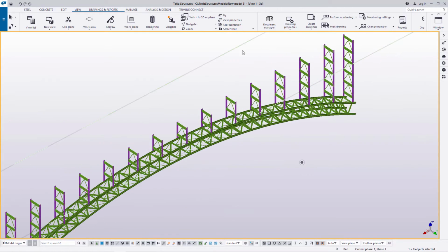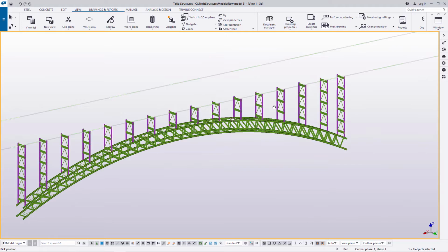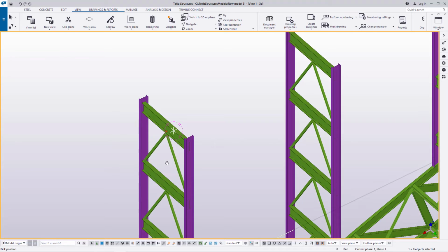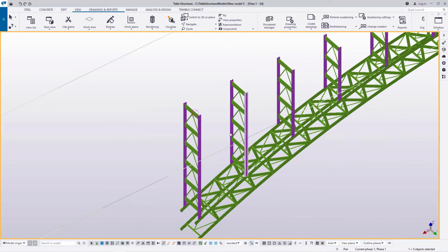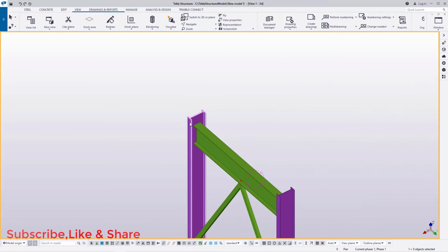Now this is what we have in place, and our beams are all in the right positions. Now we are going to another step. We are going to first of all lay the pedestrian's walkway on top of these beams. Remember, there's a lot to be done. First of all, bracing these trestles to each other so that it is a rigid structure that will be suspending our pedestrians walkway on top here.